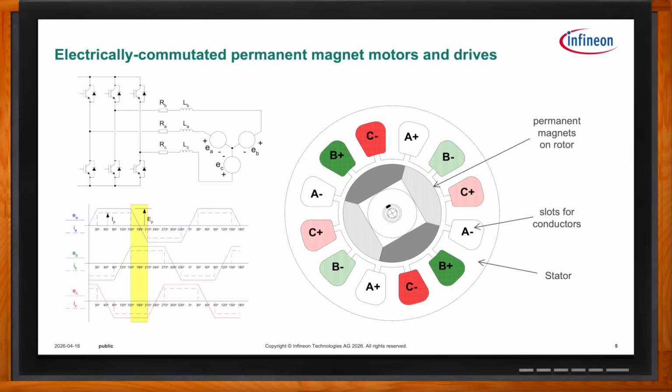And by energizing these coils in a particular order, we can create this continuous torque and pull the rotor around its full rotation. And by using all of these windings at the same time, or at least 2/3 of them at the same time, as we'll see, we get better copper utilization and therefore a smaller package to deliver the same amount of torque.